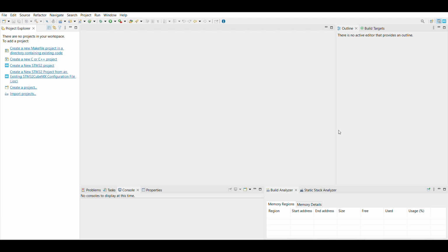In this video, I will show you how to blink an LED using an STM32 microcontroller. We will go through the basic setup, the code, and how to get your LED blinking. Let's dive in. To get started, we will be using STM32 Cube IDE. First, create a new project and select your specific MCU.